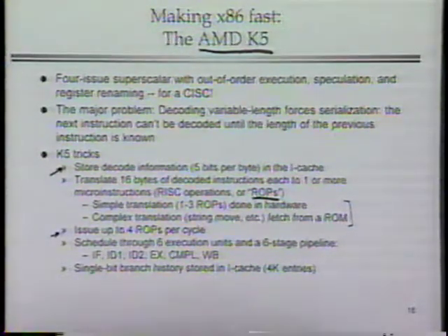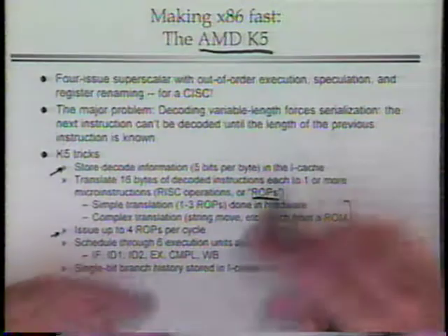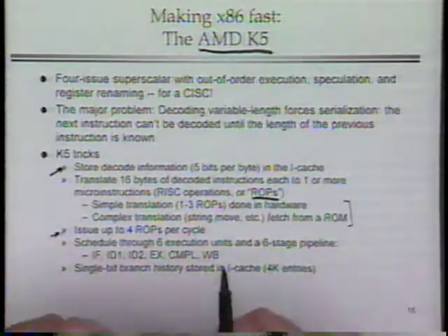Basically, when you're designing the control structure for a machine, there are two standard ways of doing it. One is that you can build state machines for a multi-cycle computer that tell you how to go from state to state to state in the execution of an instruction. Or you can build a computer inside the computer, a microcomputer that itself has little instructions that get executed that tell you what to do in the execution of each of the outer level or macro level instructions.